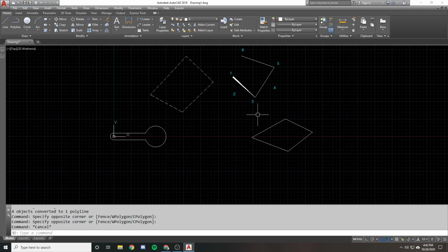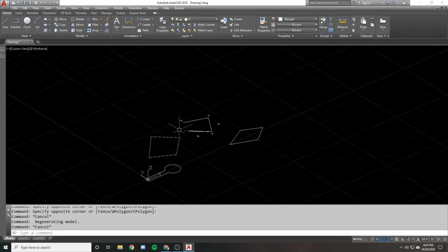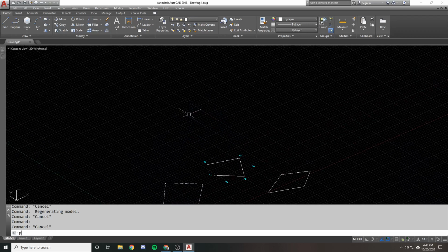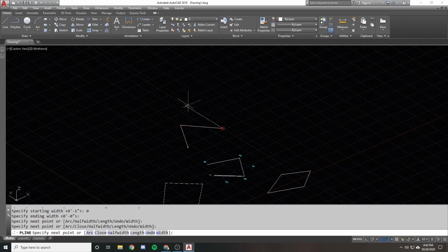Because it's important that you know about the p-edit join command, because the regular join command can also make 3D polylines. What are 3D polylines? They're like basic polylines, except they can travel in the z-axis. So let's say I have, actually, look at a regular p-line with a width of 0. All right. You'll notice that even if I'm pointing upward, even with my ortho on, it will not go into the z-axis like a line would.